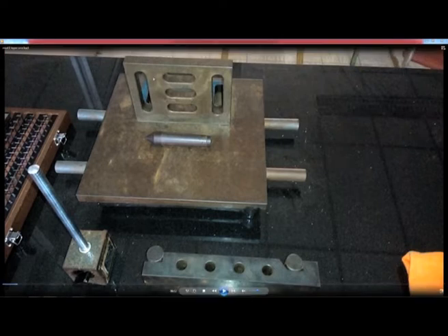We can take the help of an angle plate for proper mounting of the sine bar. This is the sine bar, these are the relief holes, and we have two rollers of equal diameter, two cylinders of equal diameter fixed to the sine bar, and then this is the magnetic stand, and then we have the slip gauge box to fill the gap between roller and the surface of the surface plate.